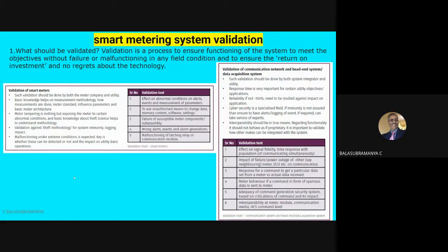You check with the representative whether the voltage level is okay, current level is okay, your communication system is fine, error is fine, whether it can be validated, whether MDMS data is okay. So those things are nothing but your validation. Validation for the communication, validation for the total structure, the total package is done on the smart meter.